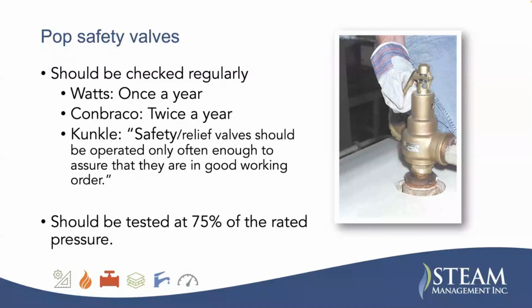The pop safety valves. When I'm doing my classes, if you were here in front of me, I'd be looking around the class. I'll say, "How often do you test your pop safety valves?" And nobody wants to make eye contact with me because nobody does it. I'll ask the group, "Well, why don't you do it?" And everyone's response is the same: "If I test it, it will leak." So you never want to do it on a Friday. These are always a Monday morning job.